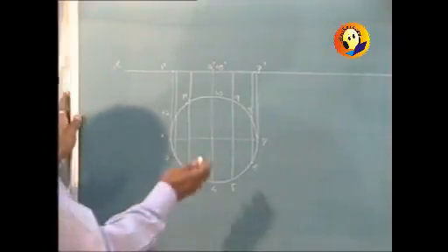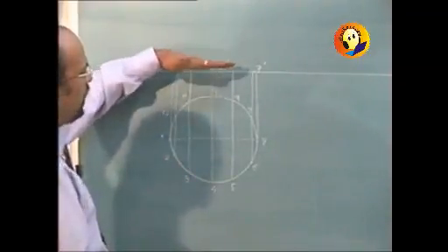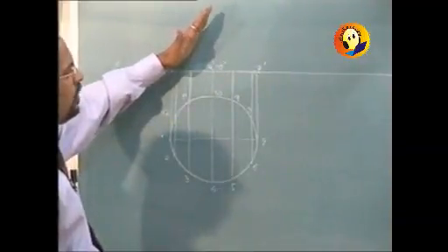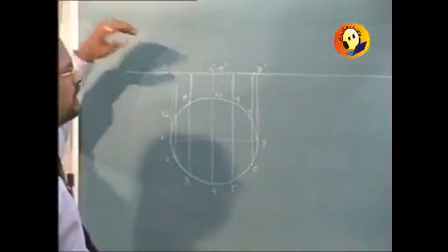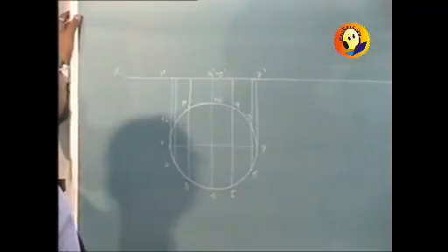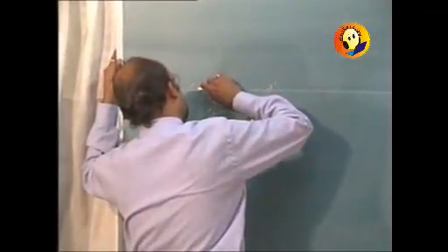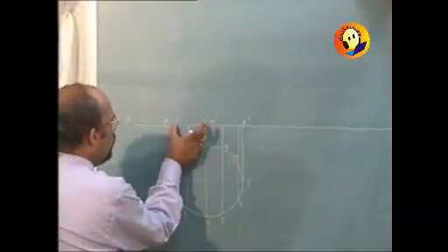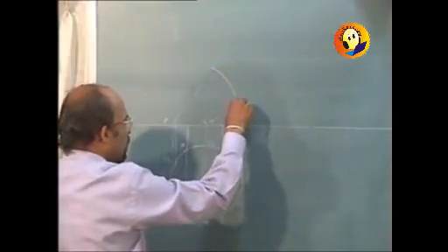And then we are required to rotate this lamina, so the line view can be rotated so that it will make 50 degrees with HP. Angle with HP will be seen in the elevation. So in elevation we are required to mark the angle 50 degrees, and then we are required to transfer all these points.